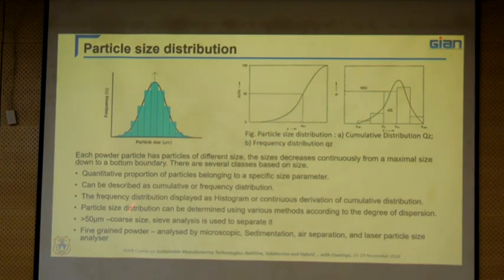And there are standard particle size distribution techniques with laser interferometry, where we can get the normal distribution curve as well as distributions skewed left or right, with the cumulative distributions. When we say the powder particles are distributed one way, right-skewed or left-skewed, it means we have more powder particles above 50 microns. That is the right skewness and left skewness. But for additive manufacturing, we should have the cumulative distribution of the powder particles as a normal distribution. This is what we need to understand and analyze for our additive manufacturing aspects.